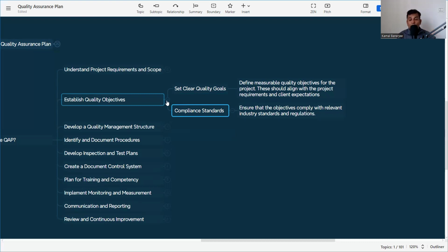what will be the thickness of the layer of the backfilling. So these are all the things we need to find out one by one, for each activity, say for example, excavation. What do you need to check? First, you need to check the material compliance. That means what will be my backfilling material. So the OMC and MDD we need to check. Sieve analysis we need to check. So first we need to check whether this material is compliant or not.